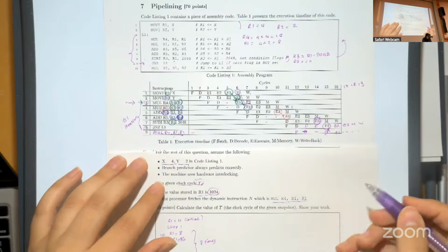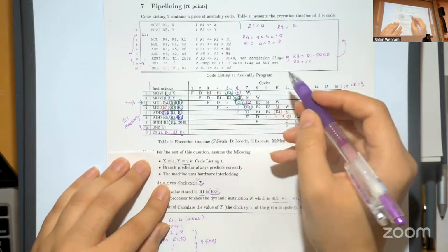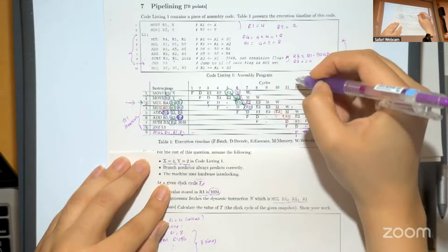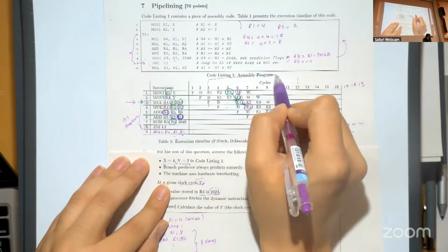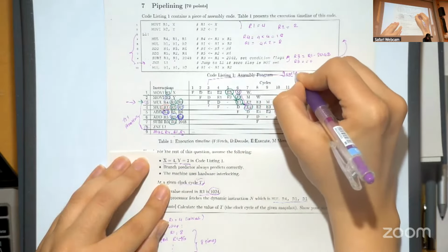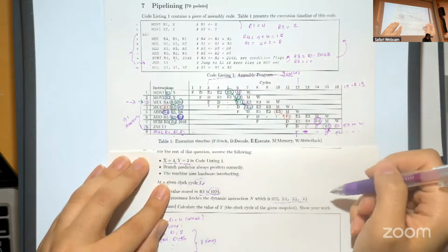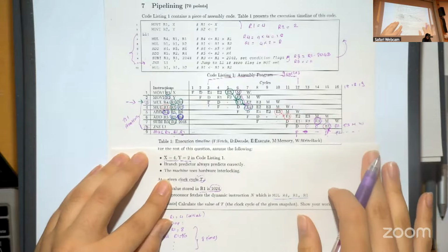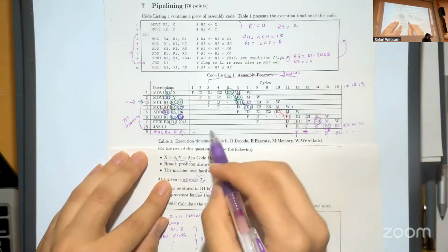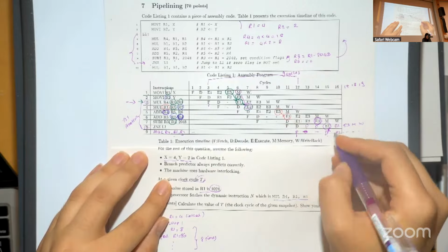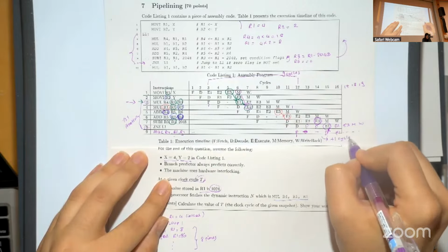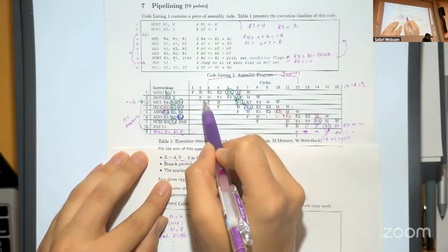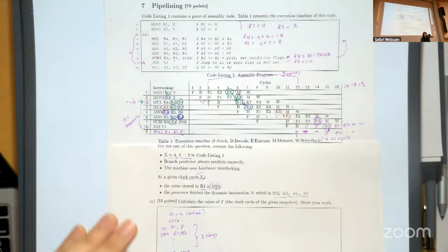So you can see that the first loop was fetched at this point, and basically the next fetch is here. It takes like 9 cycles until the next fetch. And here is a little trick, basically. That's different from the next iterations because we will have basically an extra 1 cycle here that is coming from this stall, because this is different from the first fetch that is here. So maybe this part was a bit confusing. Do you want me to explain it again?